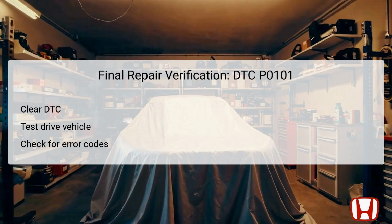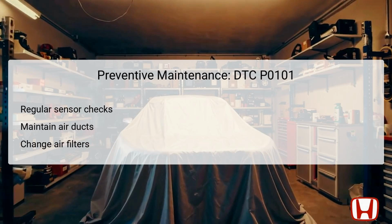Following that, conduct a test drive under various conditions, mimicking the previous steps of holding high RPMs and cruising at 40 miles per hour. Post-test drive, check the diagnostic tool again for any error codes. If the DTC P0101 does not reappear, it indicates that the repair efforts were successful and the vehicle is now functioning properly. To prevent future occurrences of DTC P0101, routine maintenance for related components is necessary.